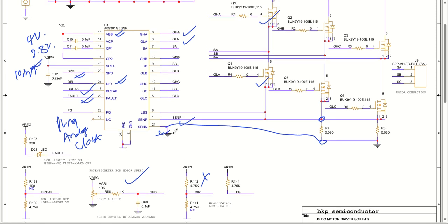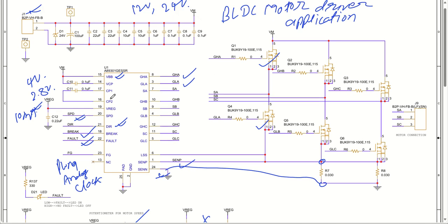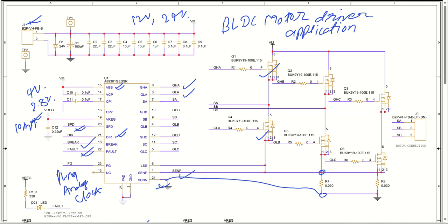So this was the complete circuit for this motor driver circuit. As you can see in the control side, we have 6 MOSFETs that we have used, and this particular MOSFET has good capability, around 100 volt and 50 ampere for drain to source current. And this connector has been used to give you the motor supply, the motor connection, at this place.